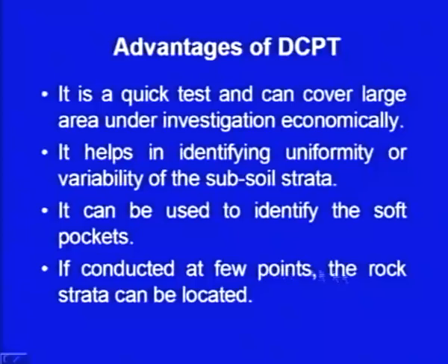So, you have to do the test on a fairly large number of points, so that if there is some bias because of some boulders etc., that can be removed, and then you can have the idea where the rock strata is located.